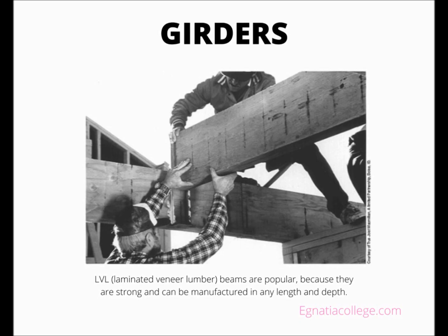Girders. Before the total length of the columns or height of the piers can be calculated, it is necessary to determine the size of the girder and its relationship to the floor joist. 3 types of girders are commonly used in residential construction. Steel beams are often used where strength is a critical factor. Built-up wood girders are constructed on the site. These consist of 3 or more pieces of 2-inch lumber nailed together with staggered joints to form larger beams.